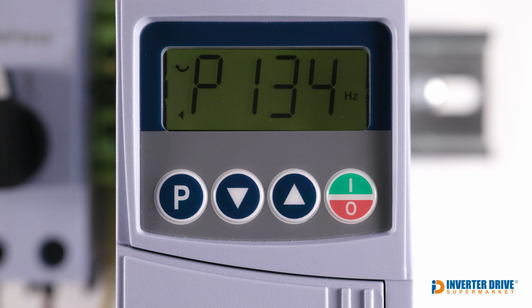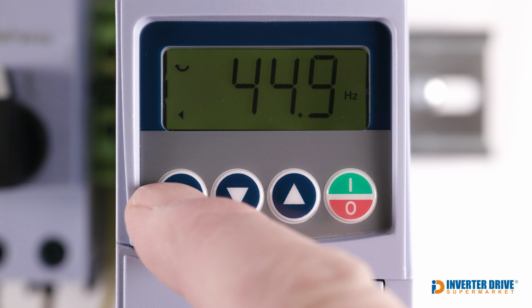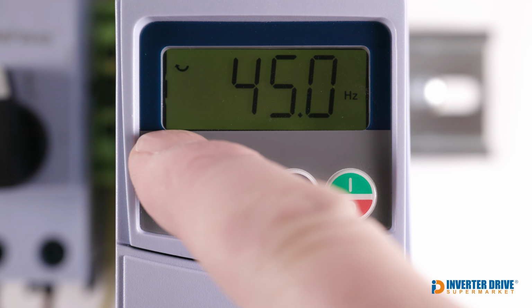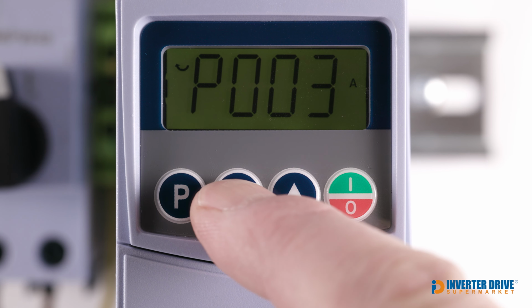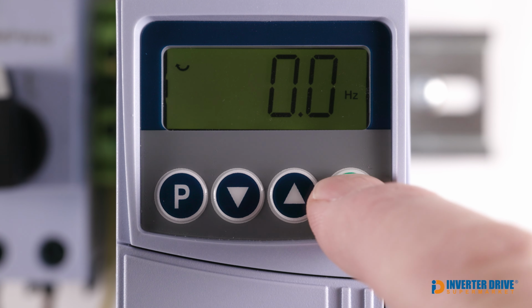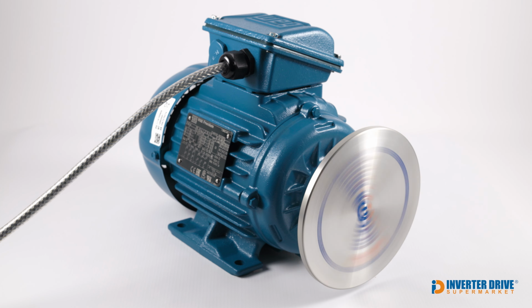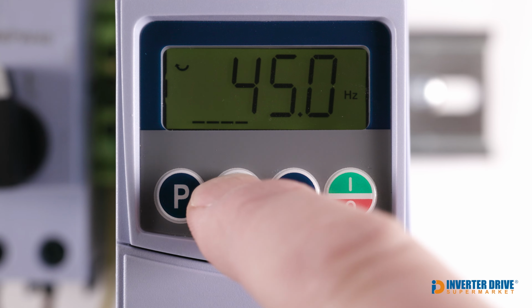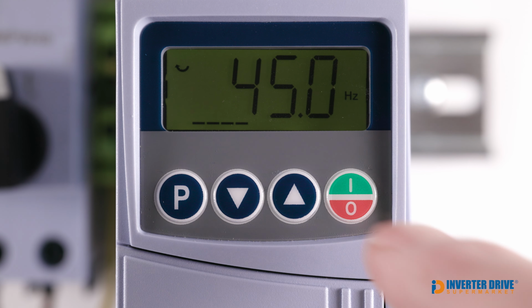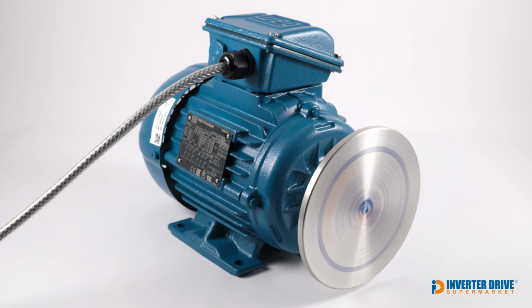The display is capable of showing up to 2 arrows representing 2 conflicts. Return to the parameter to correct the value, the arrow then disappears. Select parameter P002 again to see the output speed. Now start the motor. It accelerates to 45 Hz and won't go higher or lower. Now return the minimum to 3 Hz and maximum to 50 Hz.